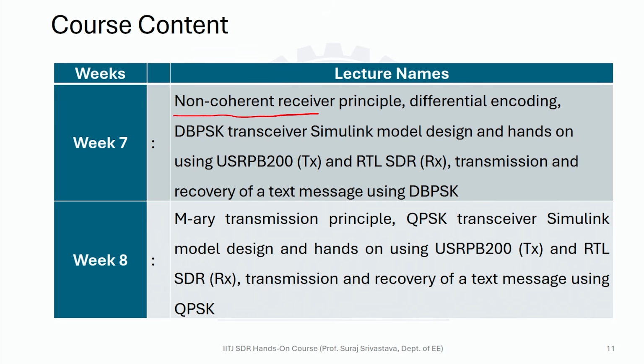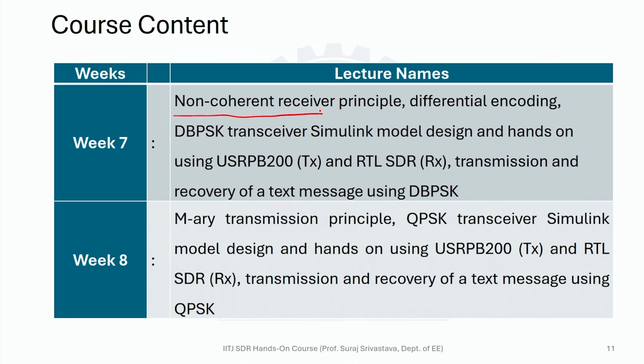So as we mentioned, when we go for a digital modulation technique, then the phase and frequency synchronization is very essential, because even a small frequency offset can introduce a lot of bit errors, right? We'll not go into all the details of these things immediately, but even a small phase and frequency offset can distort the signal. So we'll see how we can make the digital communication techniques also robust towards these phase and frequency offsets, or in general these kinds of channel impairments.